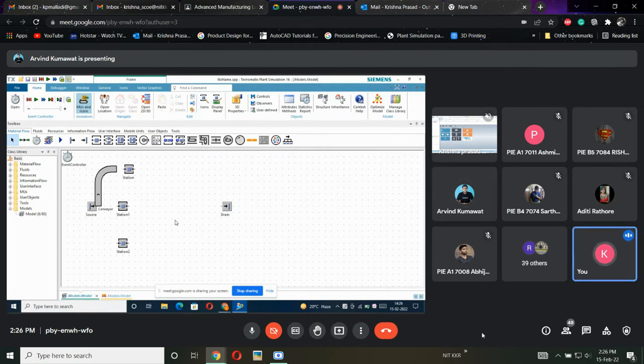If you are facing difficulties in creating any straight lines, there is one method: by using manipulators you can alter the lines and make a straight line. Still, if you face any problem, create your model in 2D, which is easier when compared to 3D. Once the model is prepared in 2D, convert into 3D and do the modifications over there. Clear?